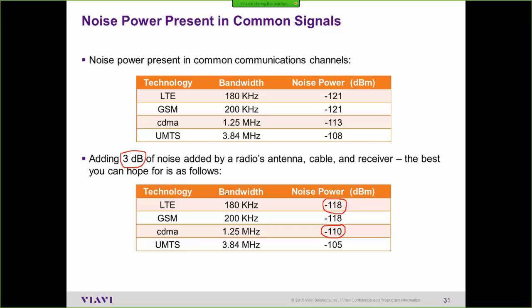But I'm going to raise that so you can begin to see what happens at a higher RBW level. Let me go up to 100 kilohertz. You see how you can't really even tell if there's something there now? Yeah, it just got more distorted.